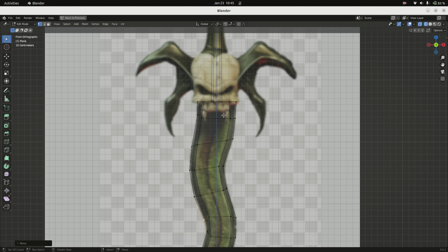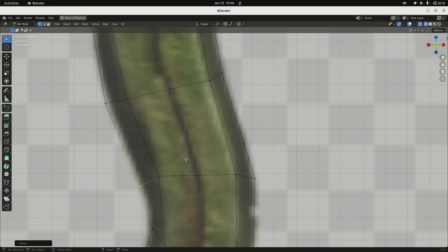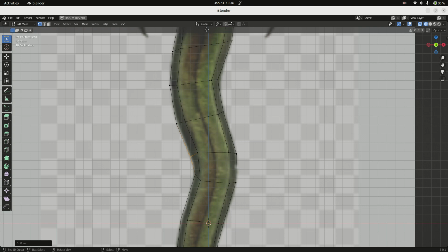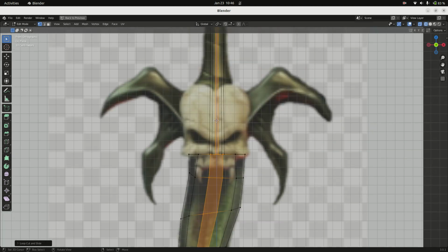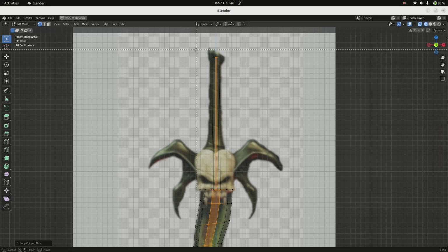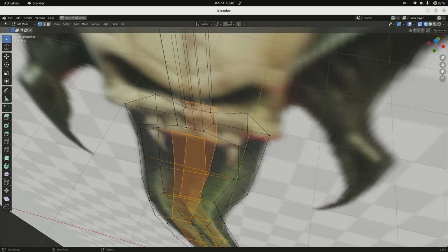All right. But there is more detail here that I might want to add physically to this model. And that is the ridge line here. This is not a fuller, this looks like more of an extension. So I'm going to Control R, and I'm going to cut down the middle twice. And I'm just going to leave it in place, right click. I don't need the tang's additional information selected. Sometimes the tool doesn't work and you have to do it manually.